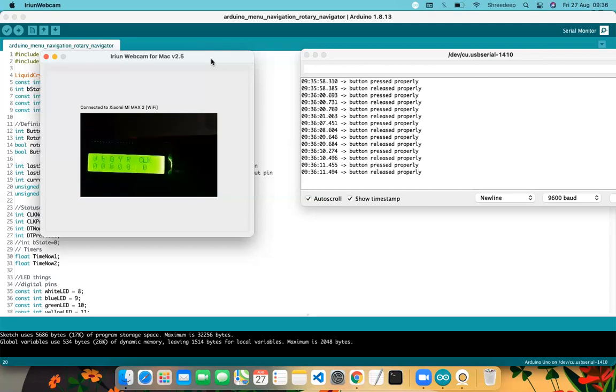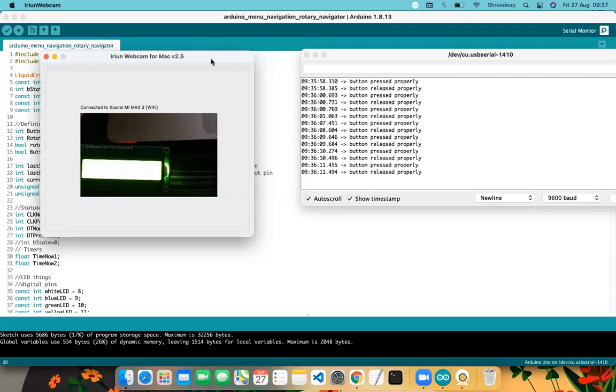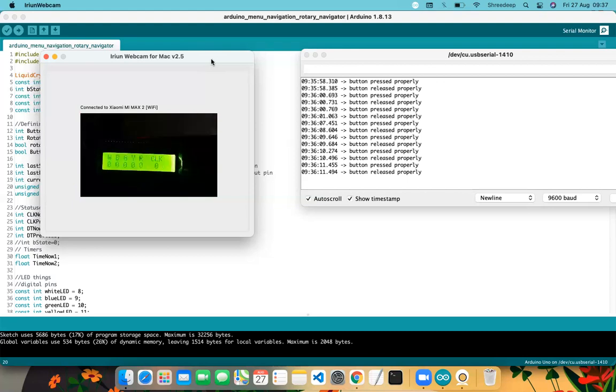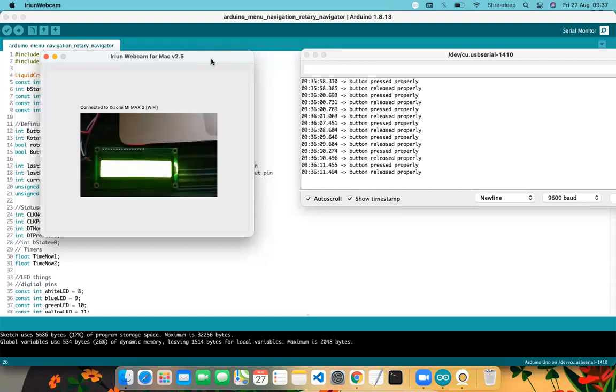The next time you press the button, it will turn off the white LED. Next, if you move the clock 0 to 1, it selects blue, and you can turn blue on and off just by pressing the button. Next, 2 means green, 3 means yellow, 4 means red. And similarly in the counterclockwise direction. Every time the clock clicks, the rotate count never falls short of 0, and it never goes beyond 4. So 0, 1, 2, 3, 4 again comes to 0. And 4, 3, 2, 1, 0 again comes to 4.